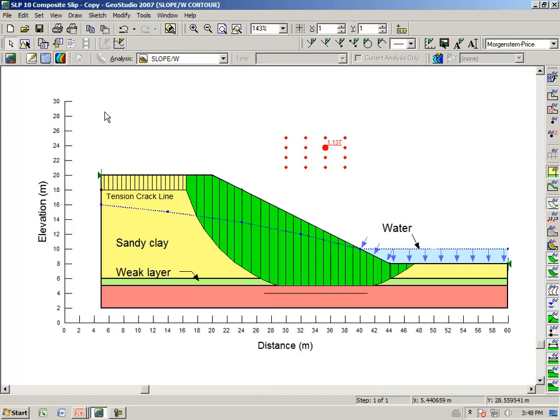It is worth noting here that the radius line can be within the bedrock. In actual fact, the radius line can be outside the geometry completely. It is just a mechanism whereby we compute the radius to create a circle, but when the circle hits the bedrock, then it follows along the top of the bedrock.